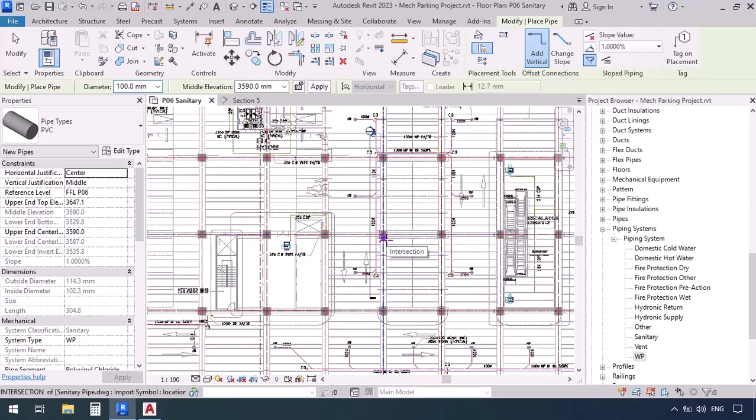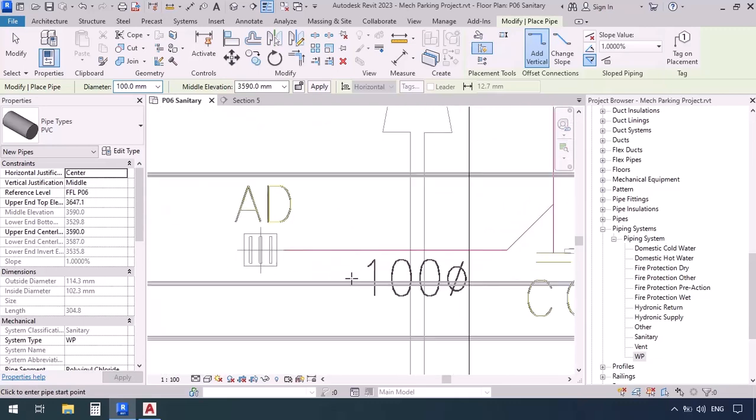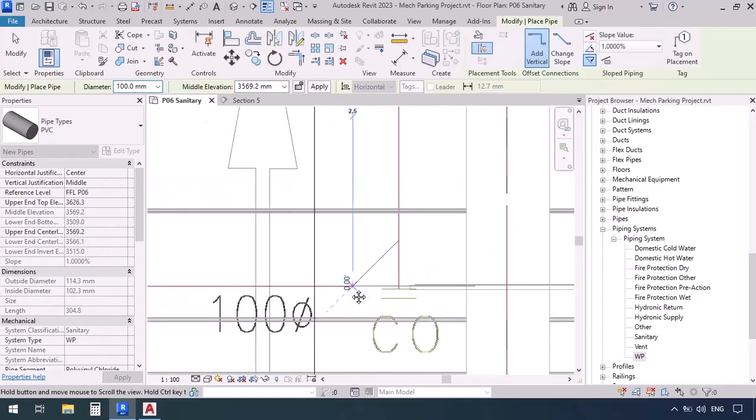By now we've adjusted all the other settings and we can start to draw. So first I'm going to zoom in a little, then somewhere near this area drain, for example here, not inside the drain. I'll tell you about connecting pipes to drains later on. So click. Then I'm going to go along the plan and click again. The fittings that we have for drains are actually 45-degree fittings, meaning that I have to go further right along the plan and click where I need to.